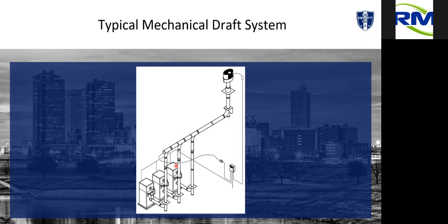So there's a couple ways of overcoming that. You can oversize the system to where you have more volume in that header, or you can put a deeper negative, get that more on the more negative side of the system to overcome that. Or you can just use a controller that can react.